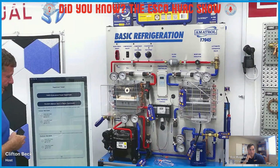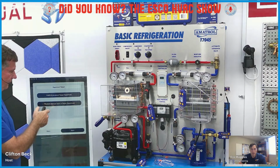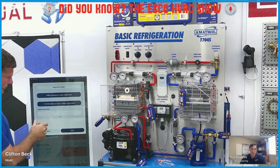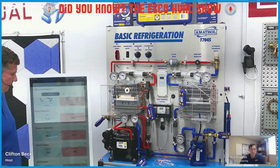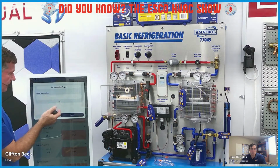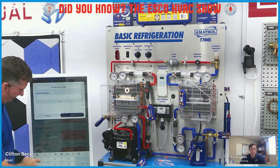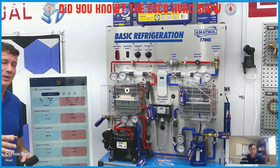That's fantastic. Yeah, because depending on the metering device, that's going to be quite a variance. Exactly. But obviously, with TXV or EXV, you're going to have to put it in because that's going to auto correct for you. So we would just pick on that one. Let's just say 10 degrees. Perfect. Okay. And let's just go ahead and do a subcooling. And just for consistency, we're just going to do the same thing. Right. Just for this particular experiment.